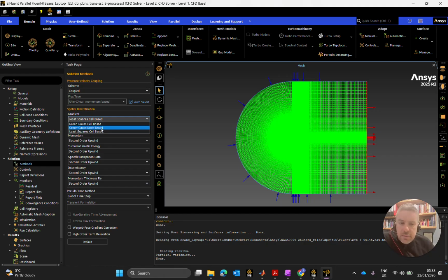And a lot of these are fine on a very structured mesh. If I had an unstructured mesh, I would do different things, especially when you're dealing with diffusion and convection and whatnot. The least squares cell based is a good, steady, dependable solver. These others can be more accurate, I believe, and this one here being the most accurate, most computationally expensive. But yeah, in 3D, it's good enough when you do it in 3D. Look at these. Other than that, least squares is best.